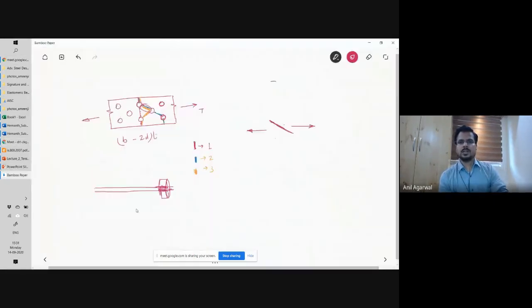Okay, fine. So in industrial structures, often rods are used. If you have a rod and maybe a nut at the end, and some portion of the rod will be threaded, then you take the root area of the thread. If I can zoom in, the threads will look like this. Threads are usually cut into the original rod shape, right?